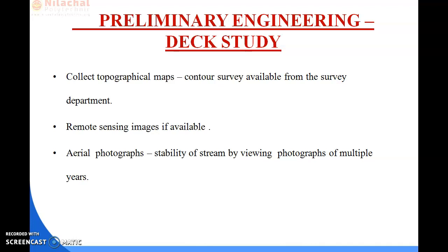Okay. So next part is the selection criteria for bridge site: preliminary study. There are different studies performed during the preliminary study, like topography, catchment area, hydrology, geotechnical data, seismology, navigation, construction resources, nearby bridges and traffic data.